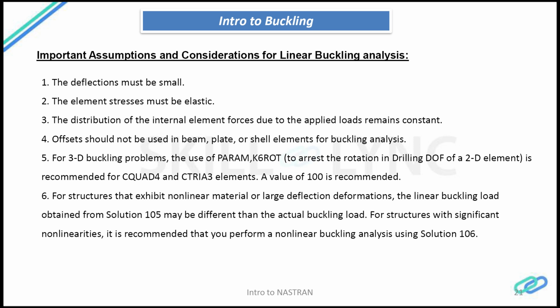If the structure is exhibiting very large deflections and so on, then the nonlinear buckling analysis would be your closest solution to the theoretical justification. The linear buckling analysis may not be worthwhile in such a case.